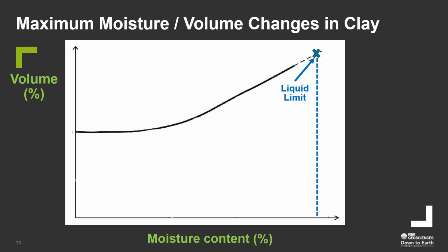So if we think about clay behavior, the clay will reach its liquid limit. If it gets to a liquid limit state, it's not really worthwhile. It's not usable as material because it's liquid. At plastic limit, there's just enough moisture in it to be workable, and we like soil if it's in that condition because we can use it. And if you then look at the difference between those two moisture contents, and we call this the plasticity index, correlations can be made with that.